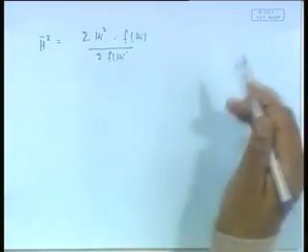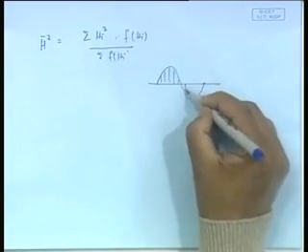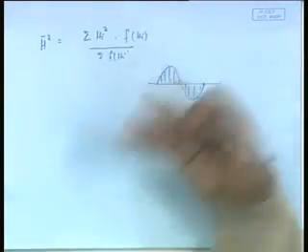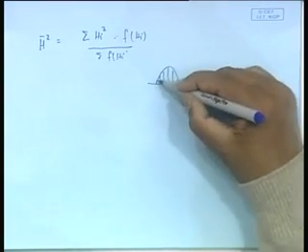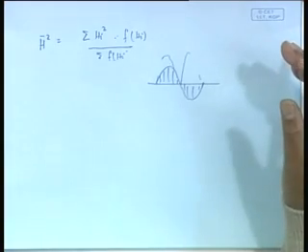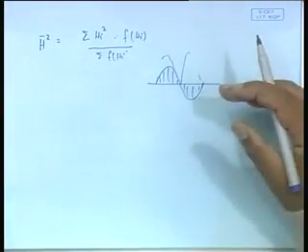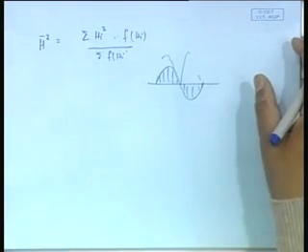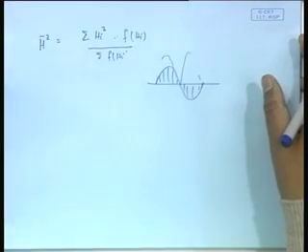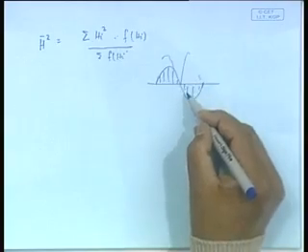You must be knowing this, that if I were to take a signal like this and take an average, the average becomes 0, because plus and minus go to 0. So that is why the idea came to square it and then average it. When you square it, this becomes like that, this also becomes like that, and you get an average. As you all know, sin theta from 0 to 2 pi averages to 0, but if you do root mean square, it is not 0. So that is why the idea of root mean square came, and why it is used more frequently than the mean value, because there can be a signal which, if it goes negative, becomes 0.